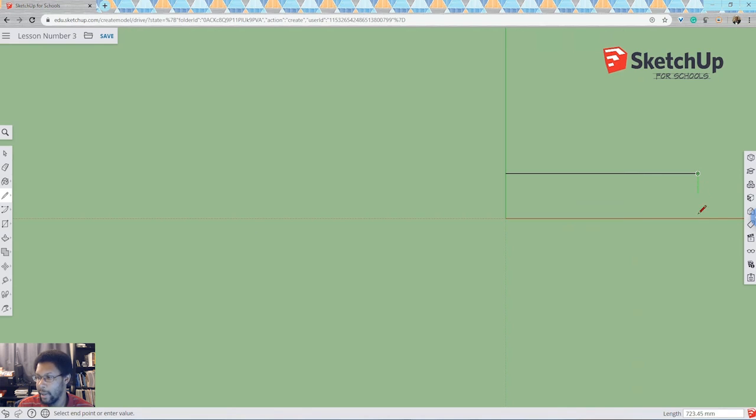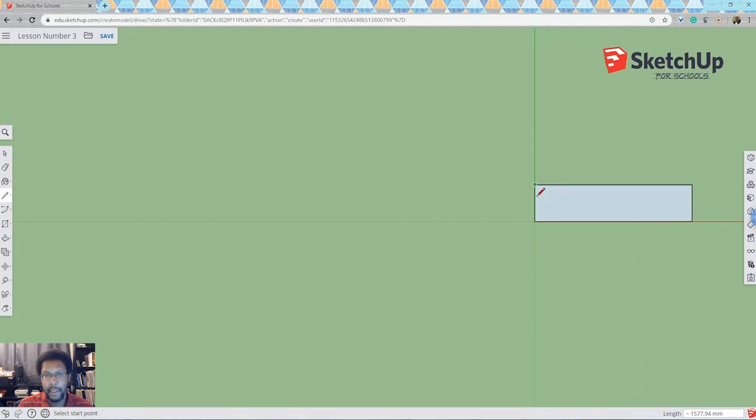So we can just drag it down, and then as we get close to the red axis right here, we can see, and I just zoomed in right there by pinching the trackpad, that it will get close, and we can just snap it right there, and then we can just pinch out to zoom out again. And then, if we were trying to make a rectangle in this case, we can just drag the cursor all the way to the point over here, that's the origin, click it again, and then we can just drag it all the way back up to where we started when we first started using this tool, and we can select it.